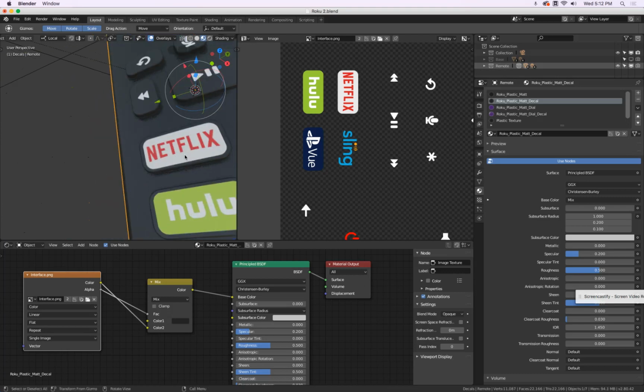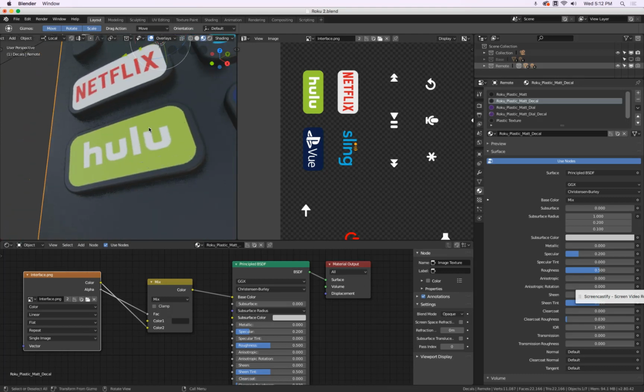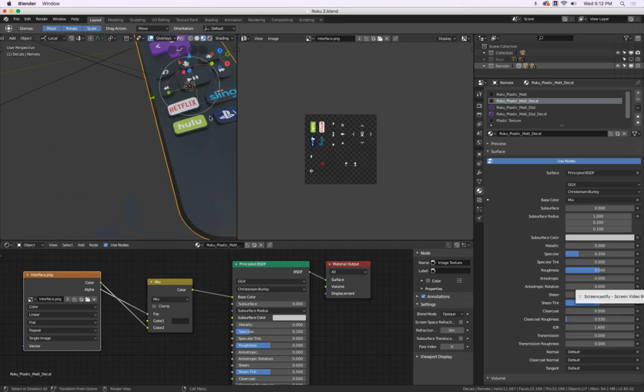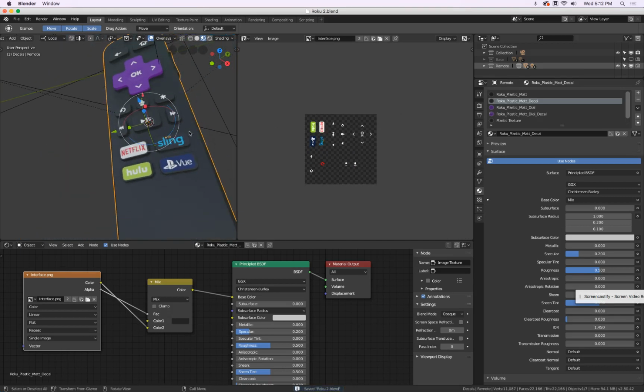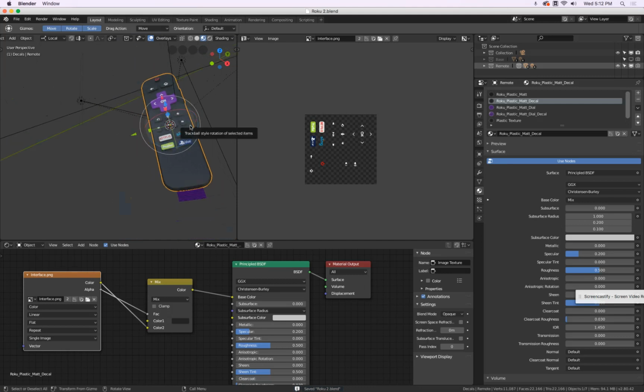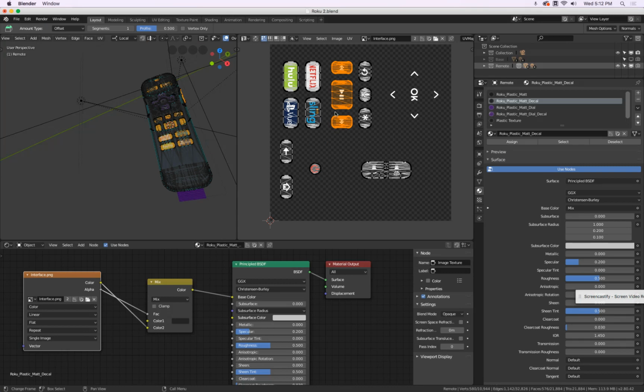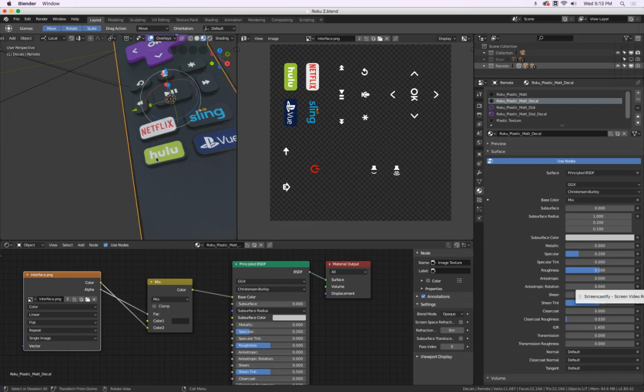So, and then essentially all we have to do now is click save, never forget it. But in terms of texturing, we're done. That's it. All buttons are done. So you see, instead of moving one image onto each button, we just have one image, and then inside the UV editor, we move the geometry to where I want to capture something from that image, and then in my material definition, make it show up here.